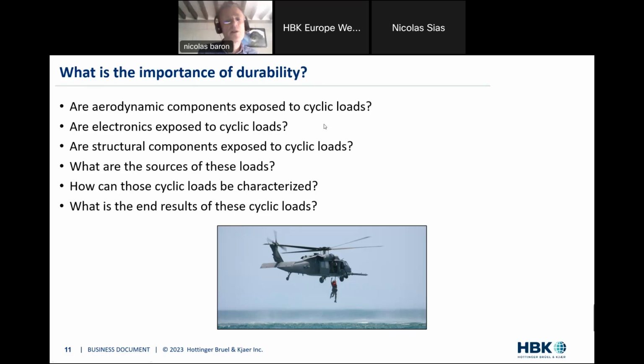Cyclic loading is really what drives fatigue. So whenever we are talking about fatigue phenomena, we have cycles involved. We'll cover that at great length in the coming minutes. But first and foremost, it's very important that you have this very clearly set in your mind for today's seminar. Cyclic loading is really necessary for fatigue phenomena to occur in our items. This is a key thing in fatigue. There must be some cyclic loading, otherwise there is no fatigue failure. There might be failures, but in case there's no cyclic loading, these failures are not considered fatigue-induced failures.